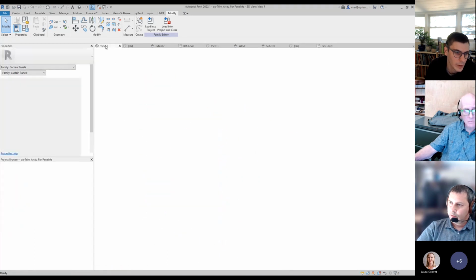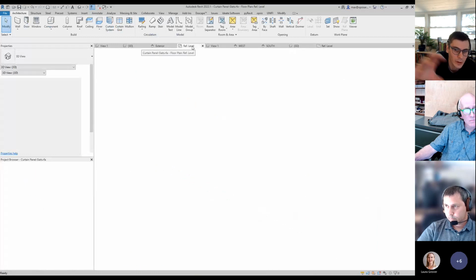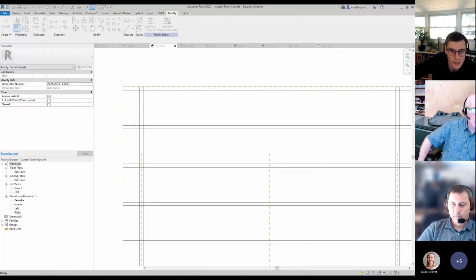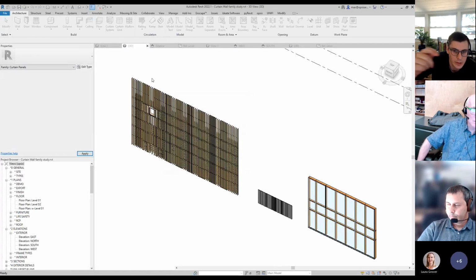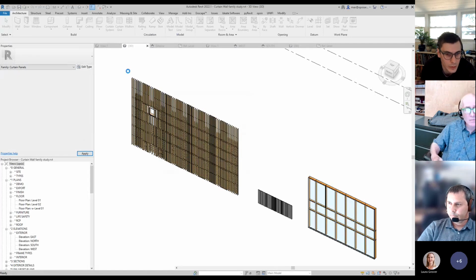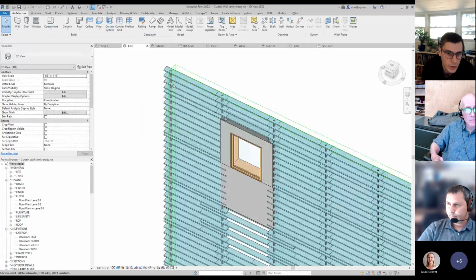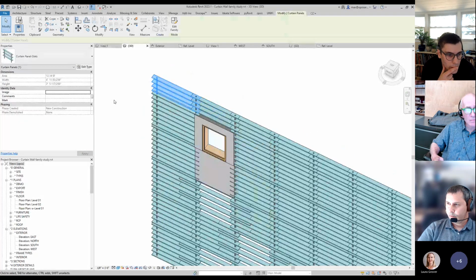I guess one way to think about it is the parameters only give you one way to speak to it from a single level up. So if it's nested into another family, you can control it from that family. But as soon as it's brought into the next environment, like another nested family or the project, you just need another parameter to tell it what to do. So each level down, it basically plays telephone and tells the next one down what the material or the parameter is.